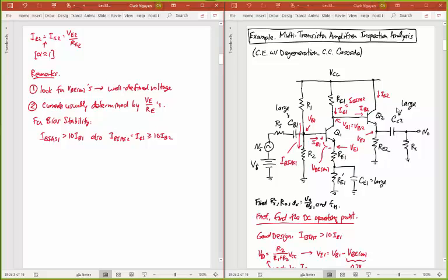Okay? So, that's the DC bias point. Anytime you're trying to design an amplifier or analyze it, you're going to have to get that DC bias point. So hopefully you've seen all the shortcuts and approximations that I make to make this a much easier problem. You could do this by plugging in the transistor equations for VBE and get some very accurate numbers where VBE is not just 0.7 volts, it's 0.70754 or something, but that's a complete waste of your time if you try to do that. Try to do it the way that I just did it here.